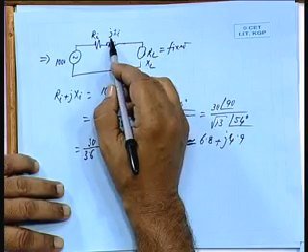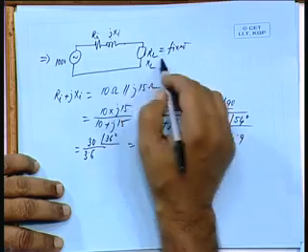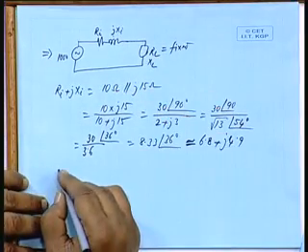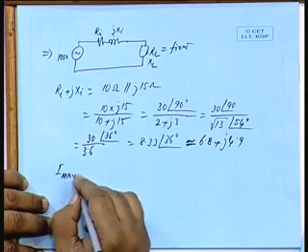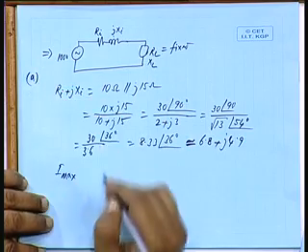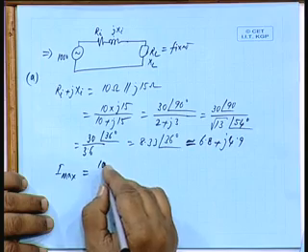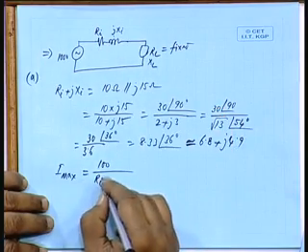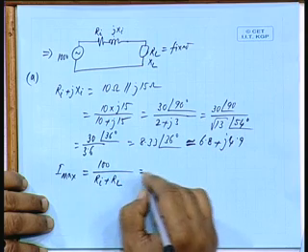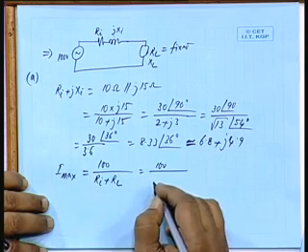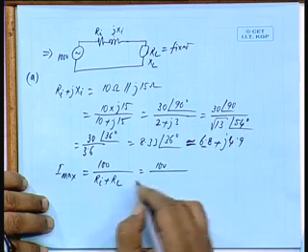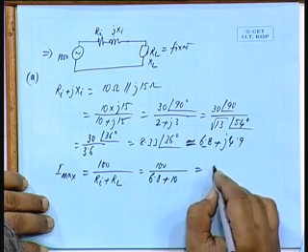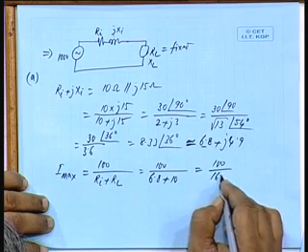When it perfectly matches with this and there is a cancellation, I get maximum current. Maximum current under this condition will be 100 volts divided by Ri plus RL, which means 100 divided by Ri, calculated to be approximately 6.8, and RL is 10. So, 100 by 16.8.